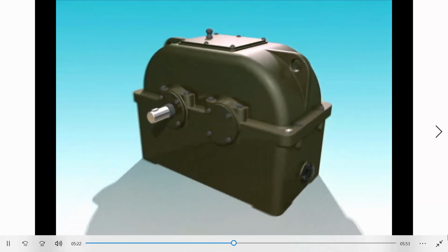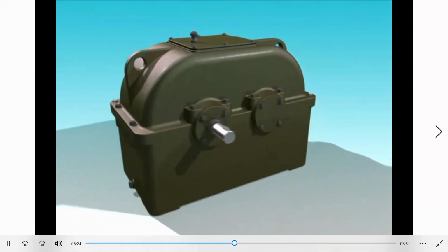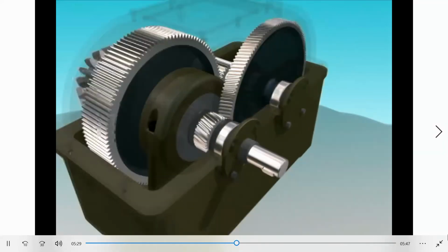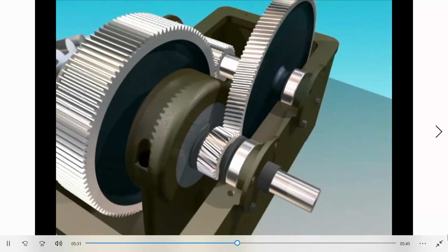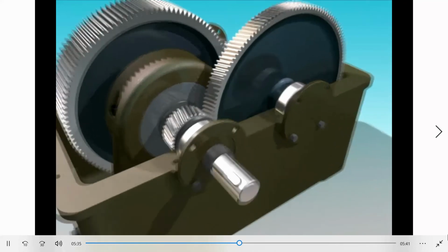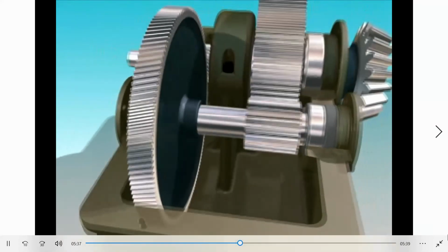The distinctive feature of this gearbox is that we use covers attached with bolts instead of end plugs, and that the high-speed gear is helical. The choice of low-speed stage is wider as it transmits more torque.